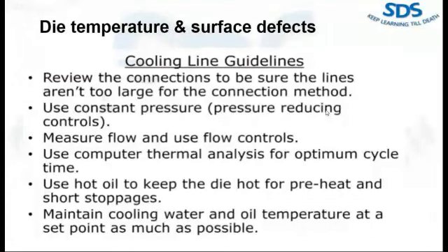Try to maintain the cooling water and oil temperature at a constant set point. And one more thing I would like to tell you: when you are using water for cooling your die, water temperature is not as important as the flow rate of water. Flow rate of cooling water is more important.